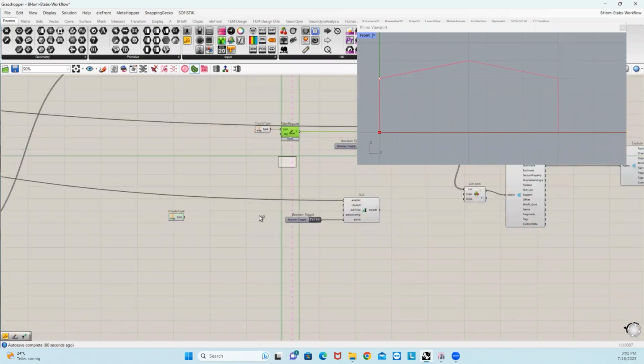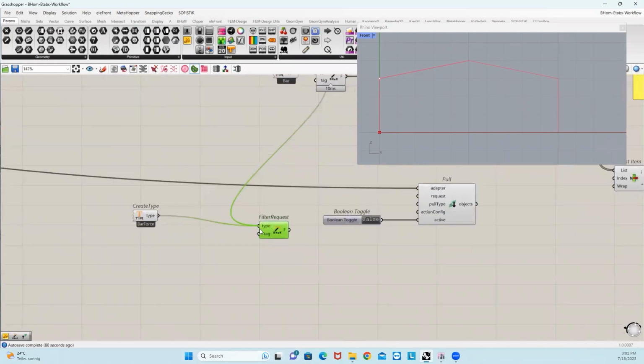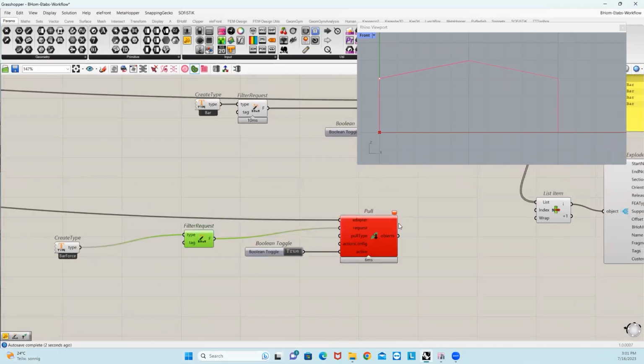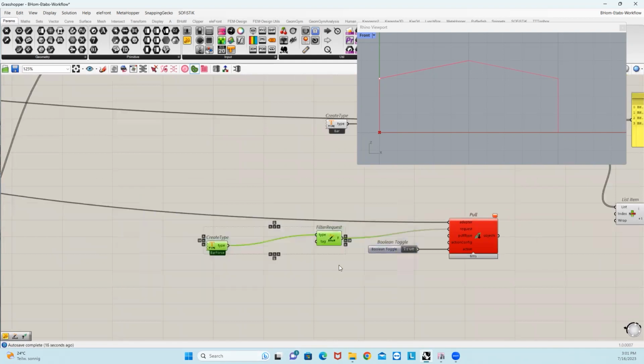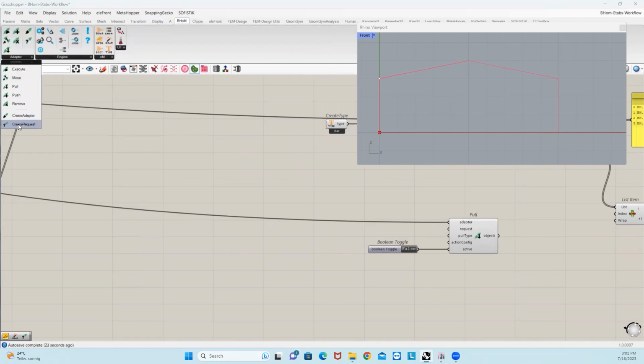If we just copy this filter, bar forces, request, now we have this error: bar force cannot be extracted using filter request. Please instead use bar result request that gives you more options for result extraction. So in this case, we will use this option of create request.